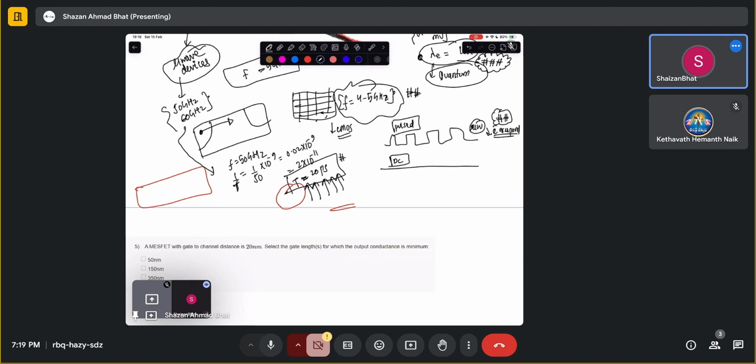That time is essential, because the electron has to at least feel the voltage for some period of time. Only then can it respond. It's not that you give it any time scale. If you give it a very short voltage pulse, it's not going to respond in a similar way as to DC. DC is like having the signal present at all times, with sufficient time for the electron to respond. But here, this particular width is very small, of the order of 20 picoseconds. So you have to make the electrons respond at that particular time. That is very tricky. There are certain ways we tackle it, and maybe in the next part we will discuss that.